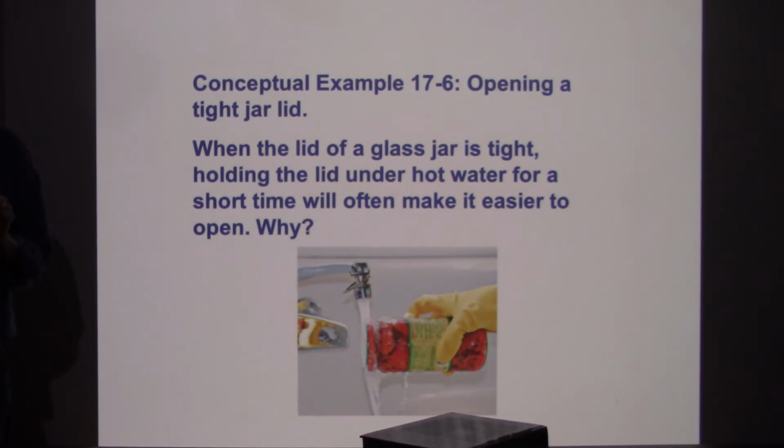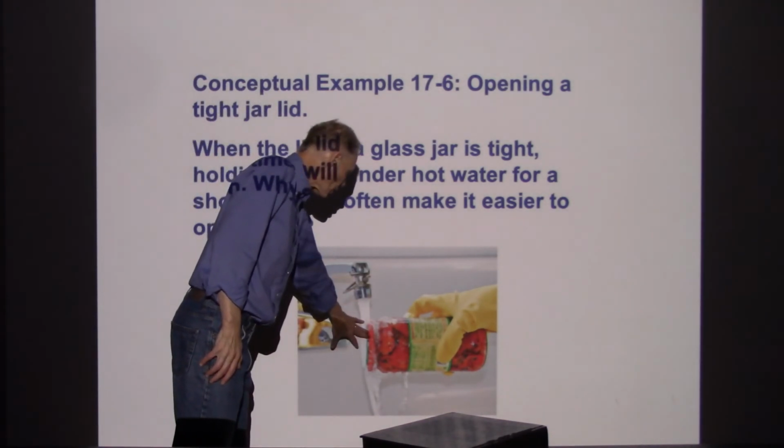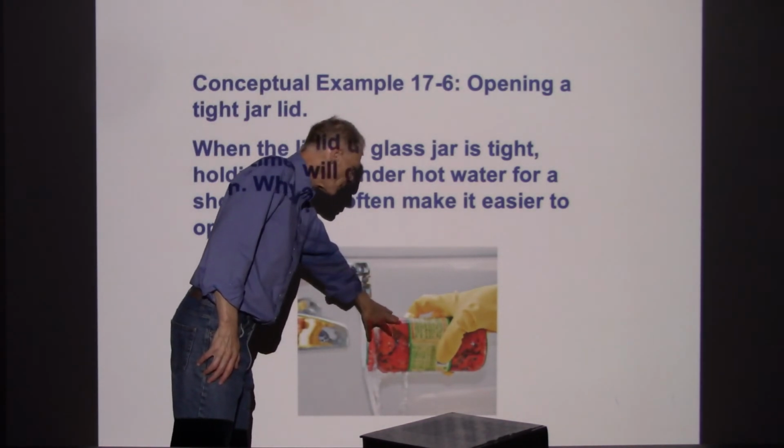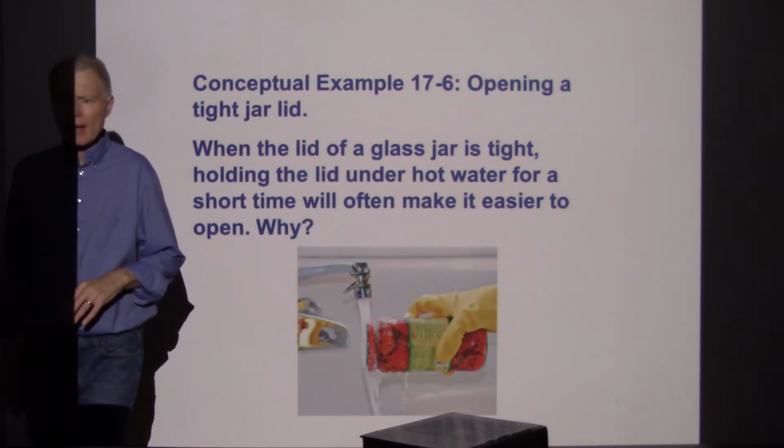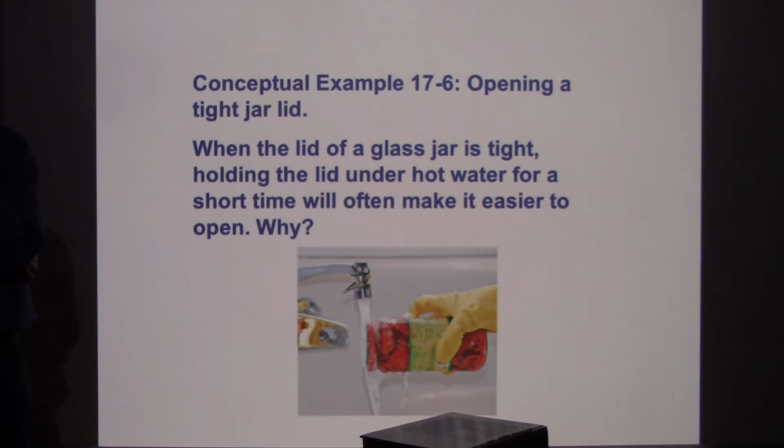So the jar lid has been put on very firmly. Now, one way to deal with that is to run a bunch of hot water over the jar lid. Now you might be thinking, yeah, but what about the glass? Doesn't the glass expand too? And what we saw in that chart is glass has a very low thermal expansion coefficient. Metals, and I'm assuming the lid is aluminum or steel, something like that, has a much higher expansion.